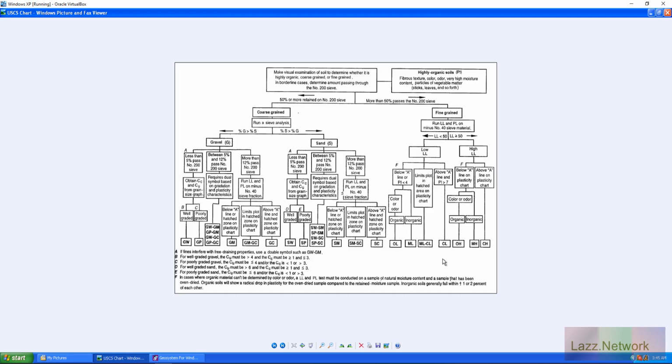Usually if it's peat, people don't want to use that. You really don't want to build on anything like that. So if something's classified as peat, it's very rare that they would want to know all the properties about it, unless they plan on using it as a construction material, or even for geotechnical work, if they're planning on installing piles or something to bypass the peat.